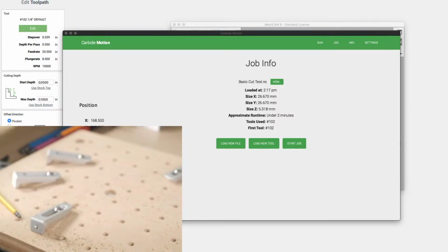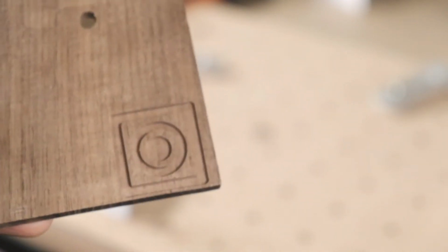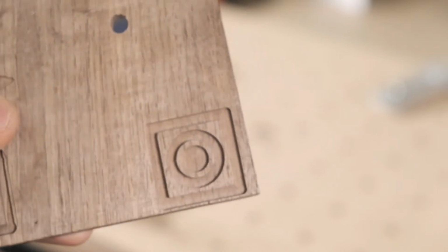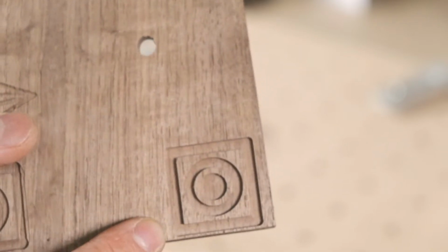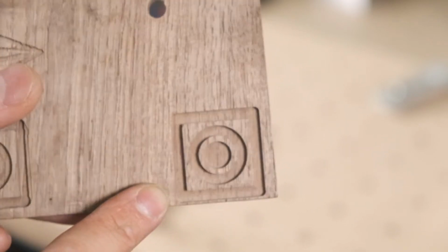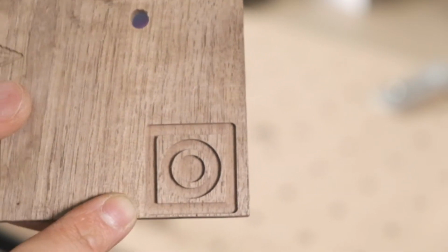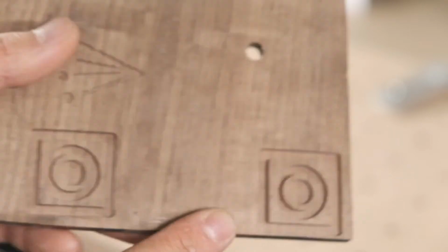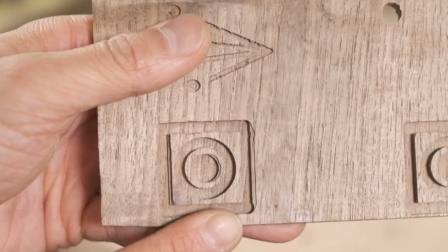Let's go full screen on the camera so I can try and focus this from afar. So straight lines, I'm using a downcut end mill. This is from our Amana, I think, 119 kit. Comes with a 1/4 inch, the V-bit, and the 1/8 inch downcut. So straight lines, clean cut, none of the issues we had in this one. So I have undone all the harm I've done to my machine intentionally, and that will conclude it for everything I've got to say here.